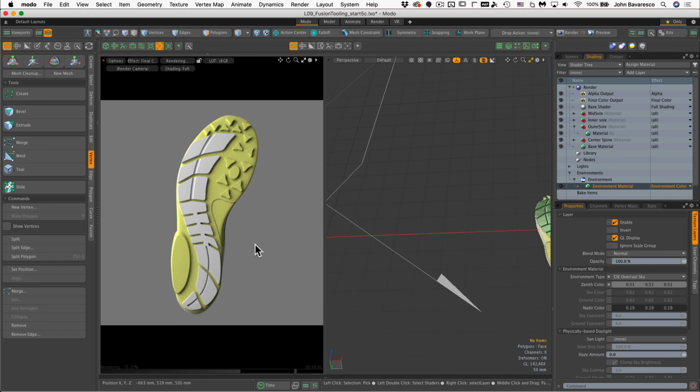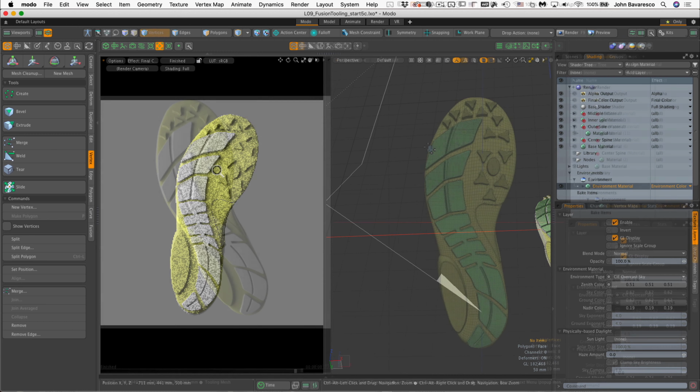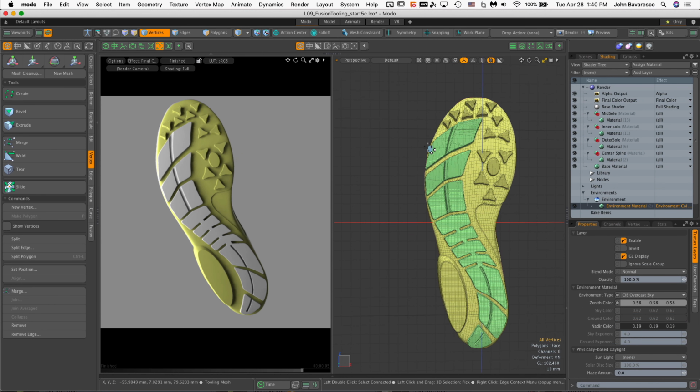They both do about the same thing, but what it's really doing is controlling the ambient lighting that is generated by the global illumination, and gives you much softer shadows and overall more realistic lighting effect. Okay, so let's go ahead and start adding materials to our model here.